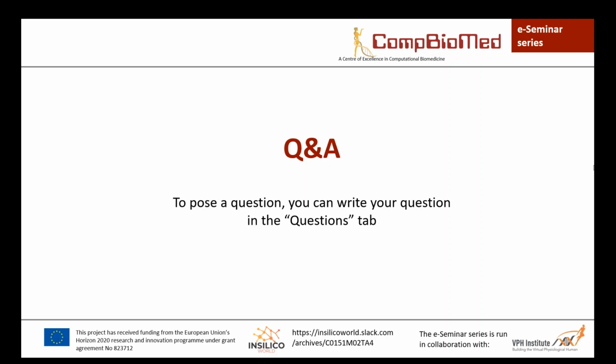So before I ask any more of my questions, I've seen that there's one that's come in on the questions tab here. This one's actually directed at Paul. CFD codes are generally memory rather than compute bound. So would features like multi-instance GPUs help alleviate this? And are there any developments in the pipeline that may help bandwidth limited applications?